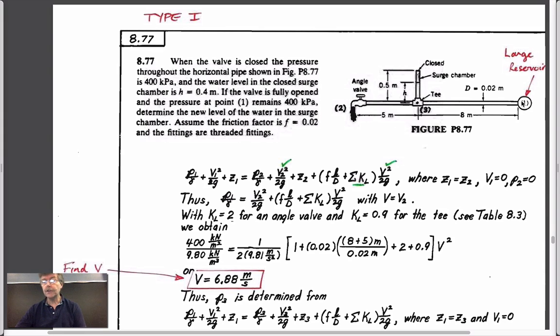So there's a horizontal pipe which is supplying some fluid out of the page. There's a connection made to this which comes out through a valve, a faucet, and it goes through a T. The T has a little surge tower in it. So the reason for having the surge tower is that maybe if this is flowing and you close this, then all the water that's flowing down here has momentum v squared over 2g. And if you're shutting this, it stops abruptly.